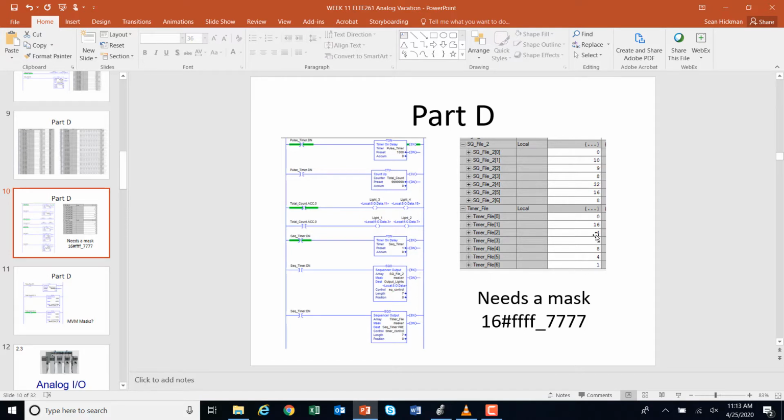and the second sequencer advances the time, and so 9 gets pushed out for 4 seconds, and then 8 gets pushed out for 1 second, and 32 gets pushed out for 8 seconds, and then it'll go through there and it'll start over. So in this case, the sequencer does the data, but we only got to do it once because the other sequencer does the timer, and this is in your book, okay?